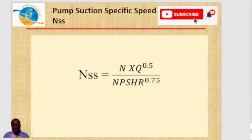Half the total flow rate for double suction impeller. You need to also take note of that. And of course, your NPSHR, which is the characteristic of your pump obtained from the vendor by the test conducted by the vendor, right? So you put this together to obtain your what? The pump suction specific speed.